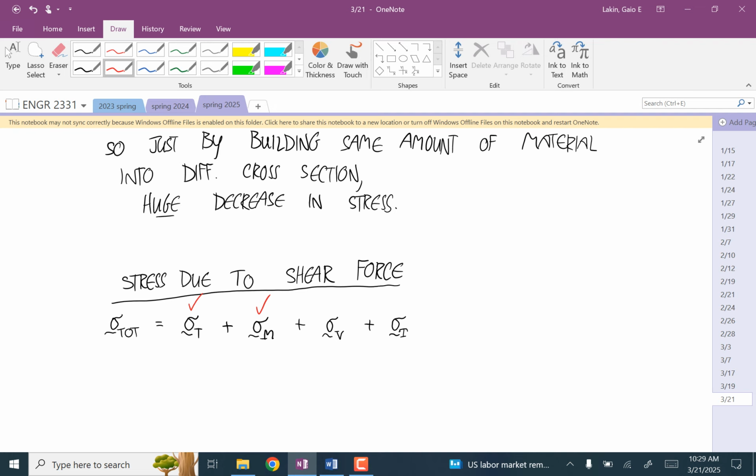Was it that it has to have a consistent cross-section? Yes, that's right. That's the first one. There's 3 of them. Same material for that? That is required for everything in this whole class. That's homogeneous. The beam has to be straight. Straight, yep. Or nearly straight. You can fudge that a little bit, but not too much. And then there's symmetric about the y-axis.